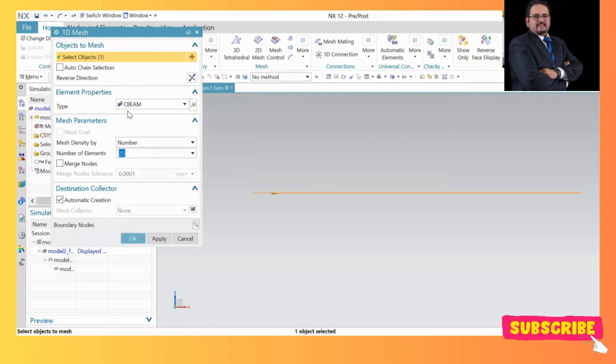By default, it would be realized that this is the beam element, because I have already assigned beam. How many divisions do you want on this line? It's up to you. Number of elements means how many small elements will be defined, or how many divisions there will be on this line. I can say go ahead with 25, right?